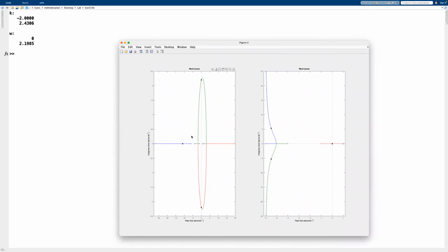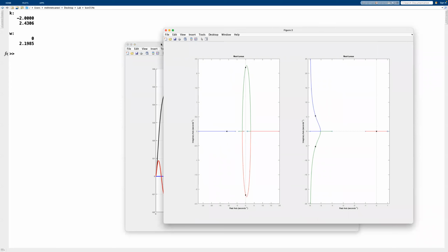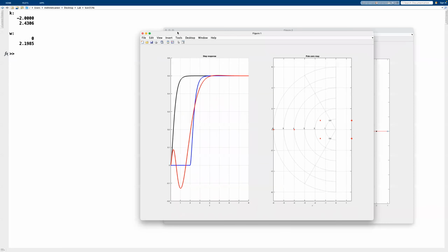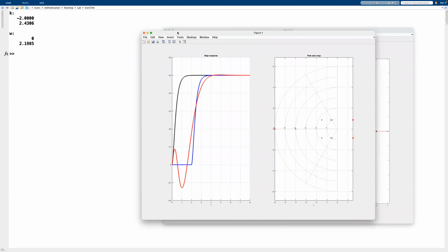And we've calculated these j omega crossings on the positive root locus or this origin crossing on the negative root locus. Now, is this the stability interval of the actual system? That's a big question here because we are using an approximation, and how are we going to rely on this? Is it reliable?